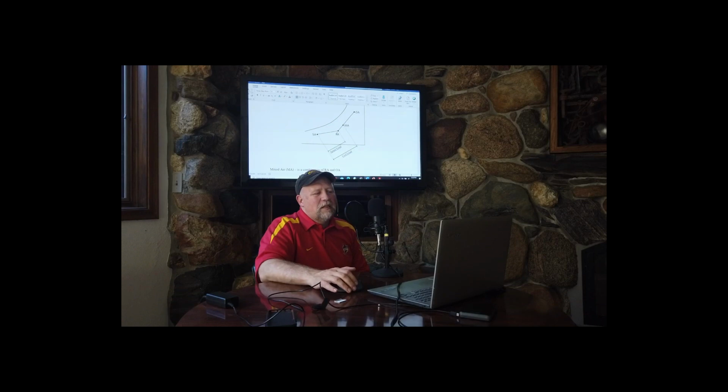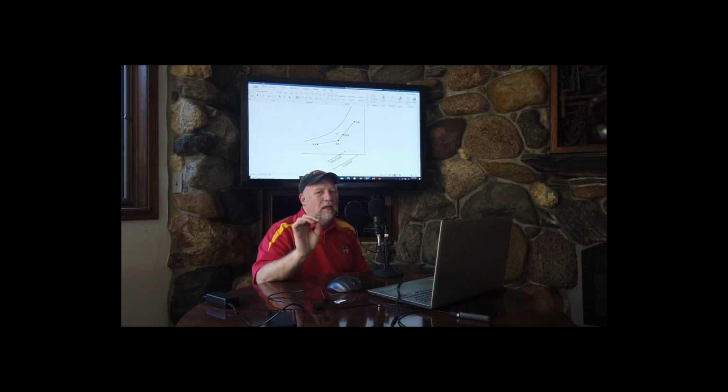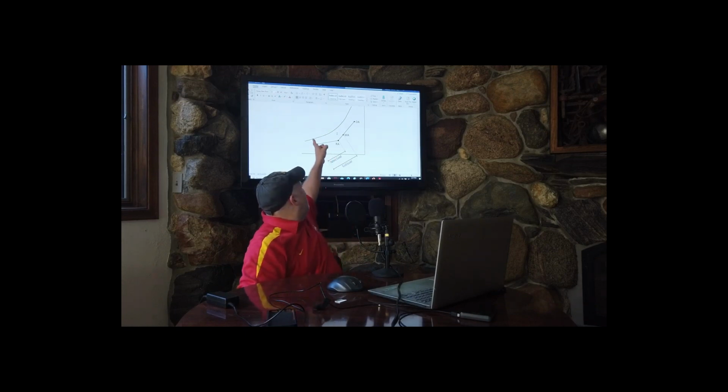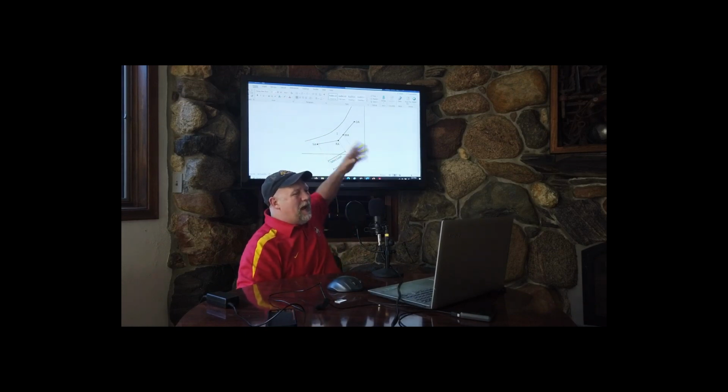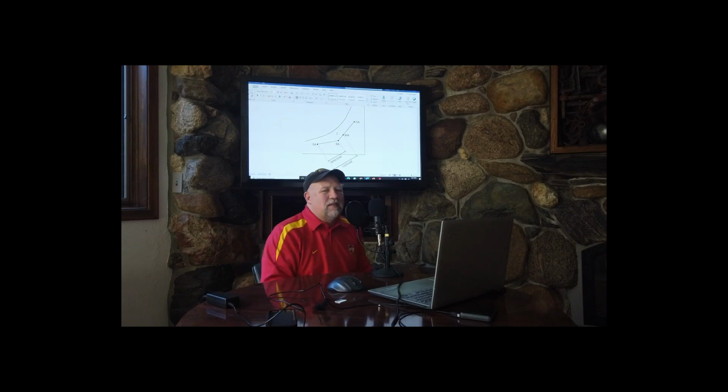For this class, a lot of times we're going to use 55 degree dry bulb, 53 degree wet bulb. Just a little bit drier. In other words, not on the saturated line. I don't want to supply air to a space that's already at saturation.